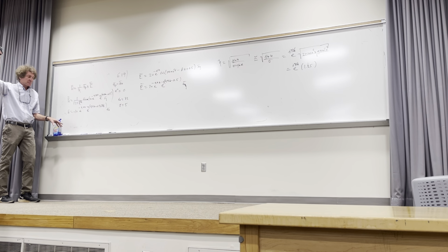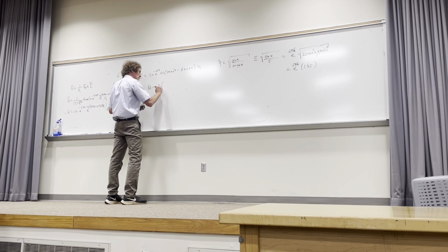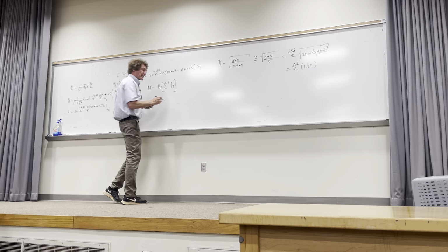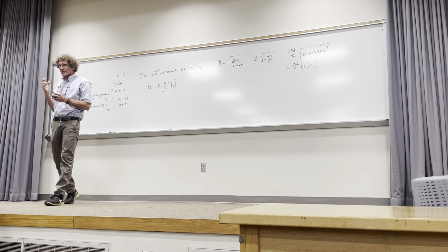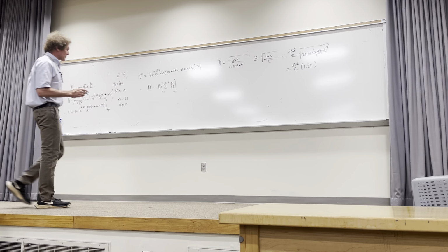Let's put it in the time domain right under here. Erase this E field. So what do I do to get it in the time domain? Got a phasor quantity. If you want a time domain quantity, technically we take the real part of e to the j omega t times the phasor domain quantity, right? That's the definition of how you do it. But really and truly, we're taking what? You're going to take the waveform, it's going to vary as a cosine, right? The real part, the e to the minus alpha z comes out in front of it. So here's what we're going to get.